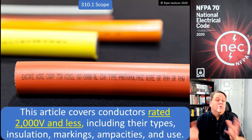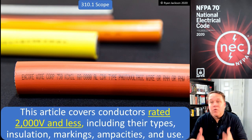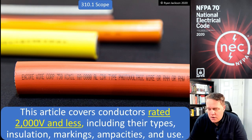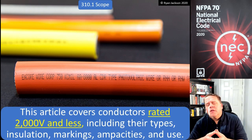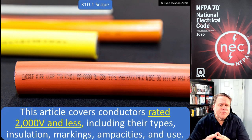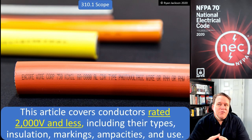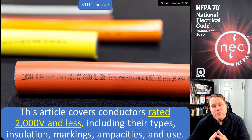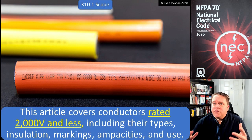Number one, they reconfigured and redid Article 310, and quite frankly, they did a great job with it. Article 310 is a much simpler and more user-friendly article than it was in 2017 and previous versions. And one of the big reasons for that is that they limited Article 310 to just 2000 volts and less. Now, let's just be honest for a minute. Most electricians really don't get above 2000 volts. You know, certainly people do medium voltage, but most of us don't.